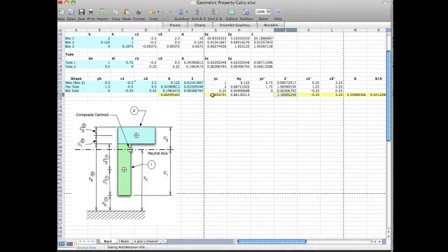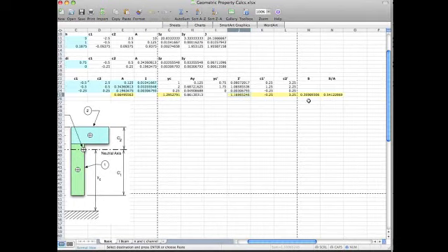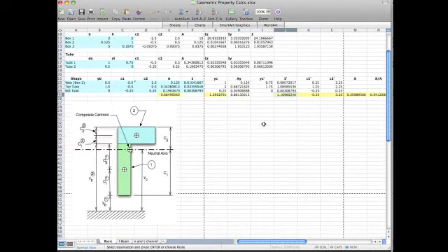That's this yellow value here, YC. Then it also does the parallel axis theorem, adds up the shapes and gives you the I about the neutral axis, and then the distance from the neutral axis down to the bottom edge, and also up to the top edge. These are the two C's. Then knowing that, you can compute the shape factor, and then of course the shape factor divided by the cross-sectional area. So that's the way it works.